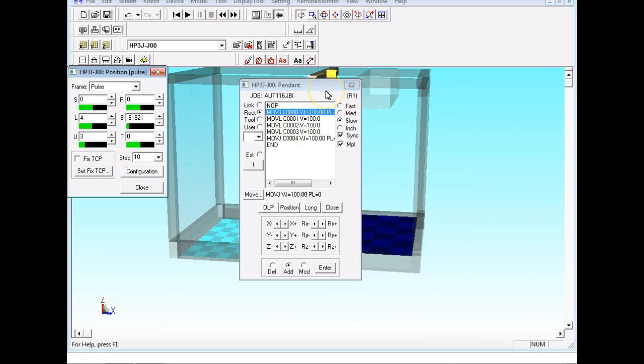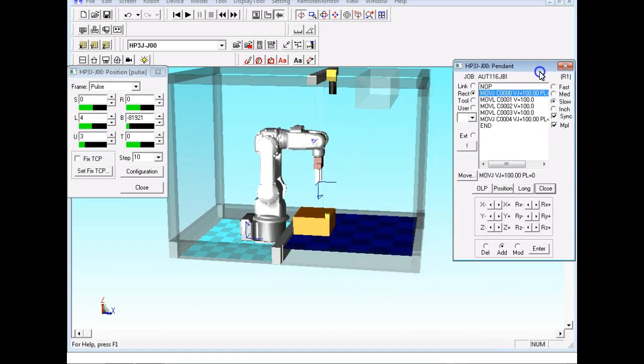Oh yeah, I could come up here now. We can't do this on the actual robot, but we can do this on a simulation. I can come up here and say, okay, I want S to go 100 millimeters, and I hit enter, and by George, it moved. But it was hard to say. Another way, a lot of your robots do it according to the Cartesian system.